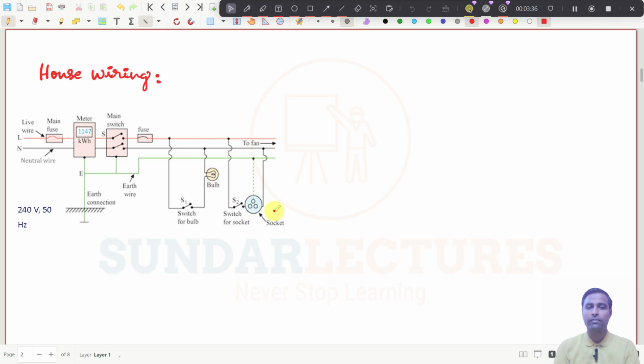And also if you have a socket like this, then the phase will be connected through a switch, and the neutral will be directly connected. And then there will be a ground wire, and this ground wire will be connected to these kinds of sockets. This is how you would have connected the single phase systems we use in commercial usages. In commercial house wirings and many places, we use these single phase AC systems.